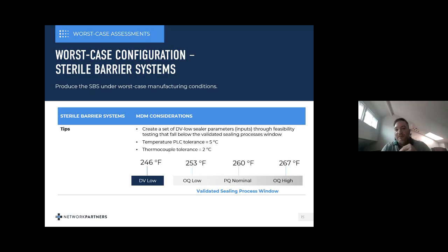Same with the carton and the shipper. Really, the shipper at 200 pound, 275 pound, you'll be fine. The shipper is meant to take the brunt of the forces. You can tell when you go through drop testing, it looks like buckling in all the edges and all the corners, but that's really what the shipper and the carton are for. At the end of the day, they remove the carton and it could have some buckling, but again, that's still considered protective packaging. So hopefully that answered your question. I would strongly recommend taking a look at the guidance in 16775. There's probably a little more information there too.